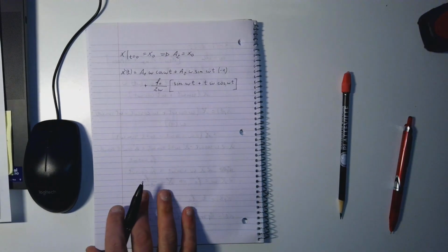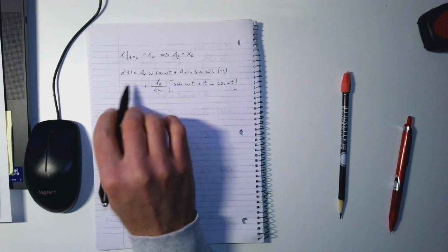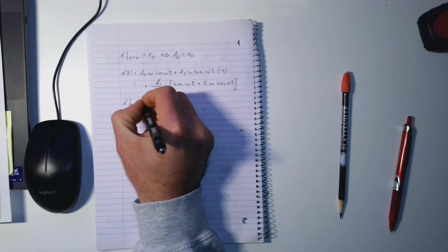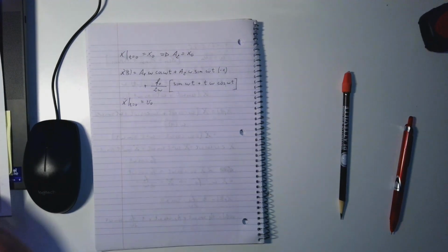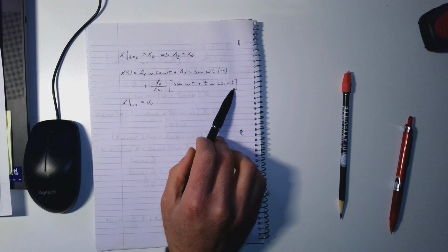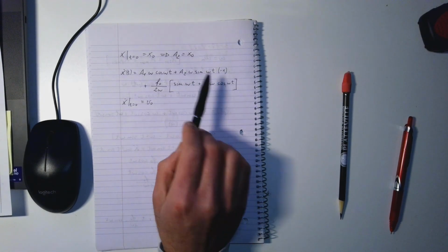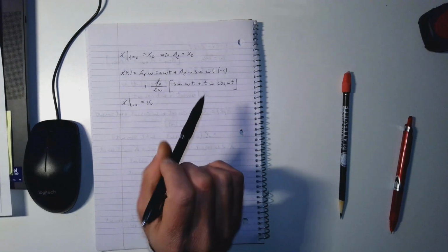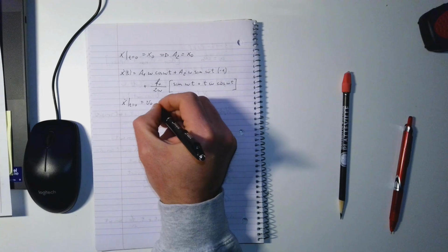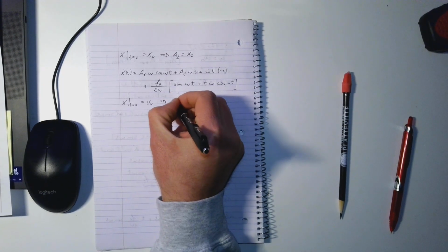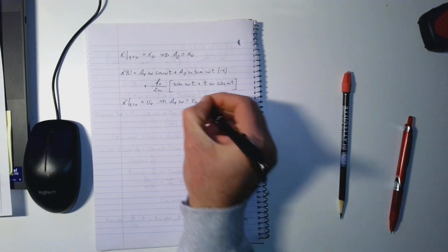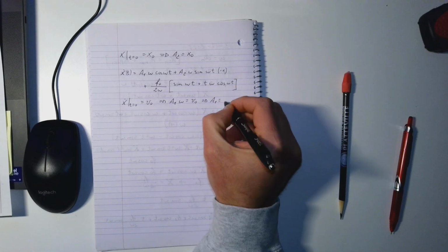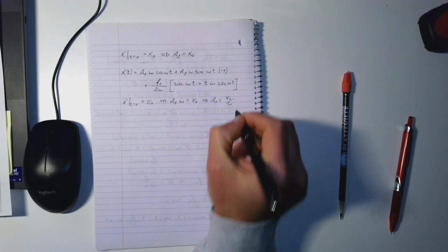Now we can use the initial condition in terms of velocity. When we plug in x dot at t equal to 0 equal to v0, again this simplifies significantly: all the sines go away, and the cosines become 1. So what we obtain is that a1 omega is equal to v0, which means that a1 is equal to v0 divided by omega.